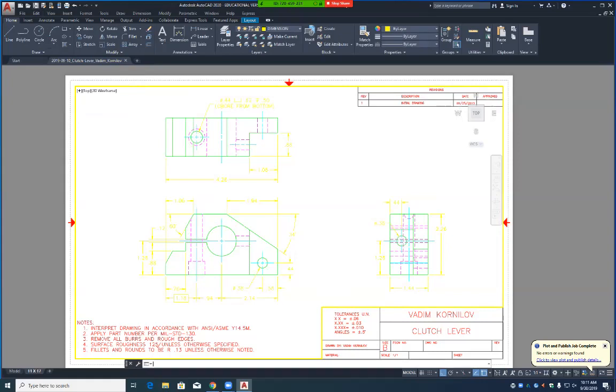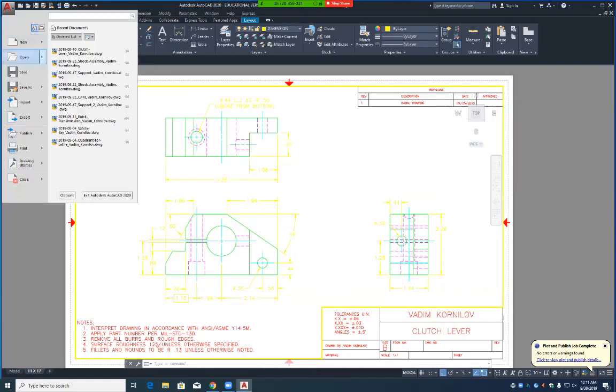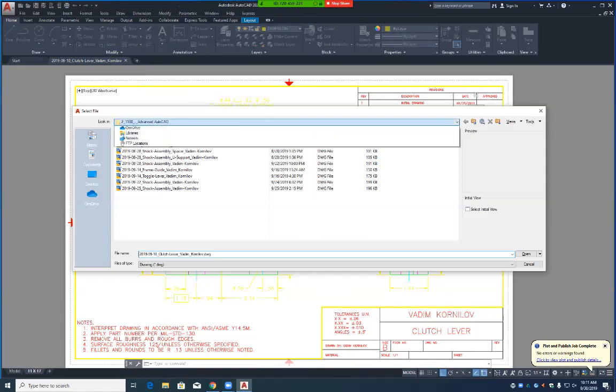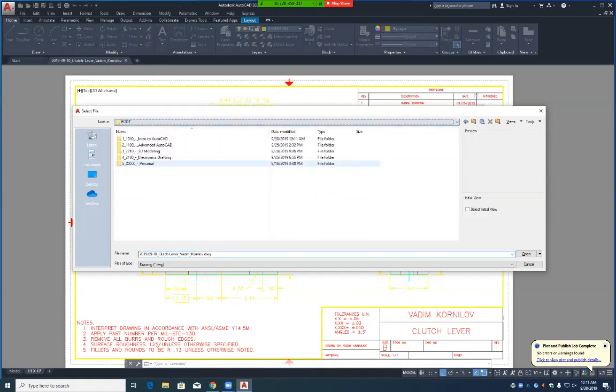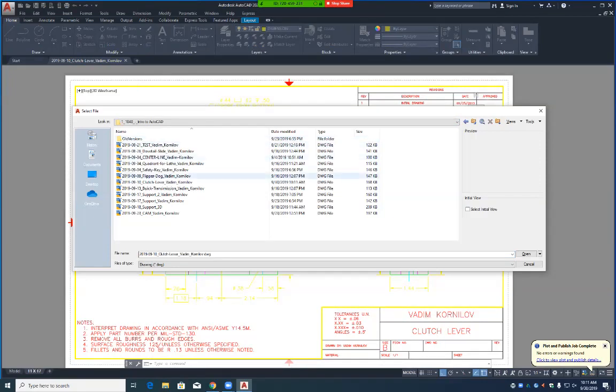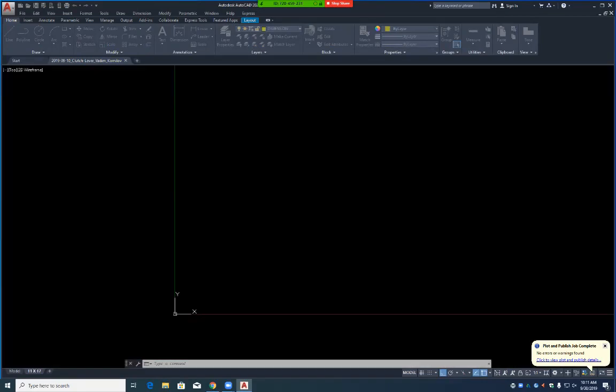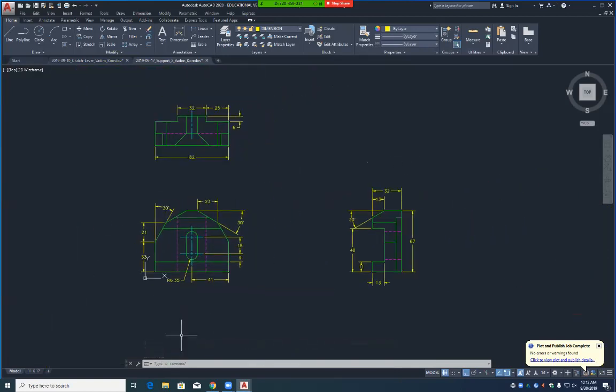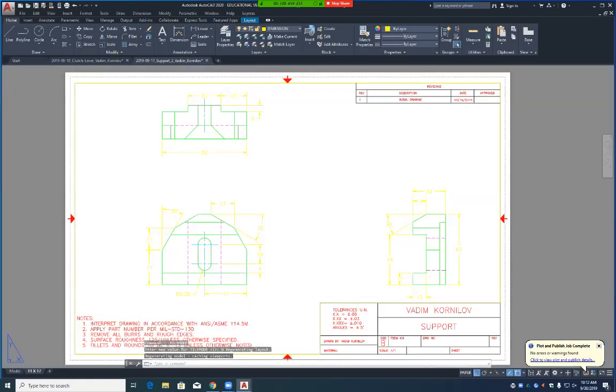So from here to here on this one would be 0.2, right? This is 0.2, this is 0.2, and this is 0.2. This is 0.4 right here, right? That's all you need to know about keyways, how to draw them. So the first one is the overall of the square, and the second one is half of it. Just like on the 3/8 and 3/16. That's 3/16, that's 3/8. Got it.